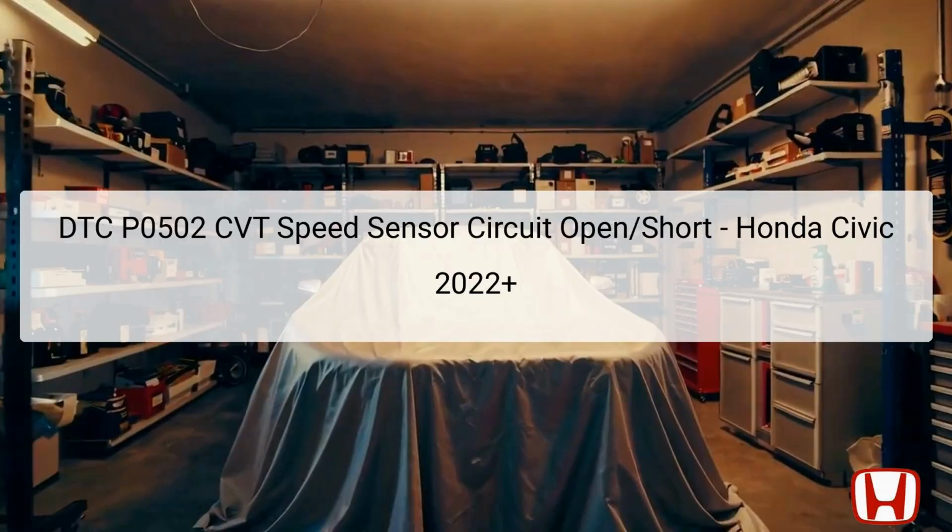The DTC P0502 indicates a problem with the continuously variable transmission CVT speed sensor circuit, which the transmission control module, TCM, uses to monitor the vehicle's speed. This issue arises when the TCM cannot accurately detect the signal from the CVT speed sensor while the secondary driven gear rotates. The failure of this sensor can lead to improper transmission function, since it is crucial for the engine management system to optimize gear shifting and overall drivability.